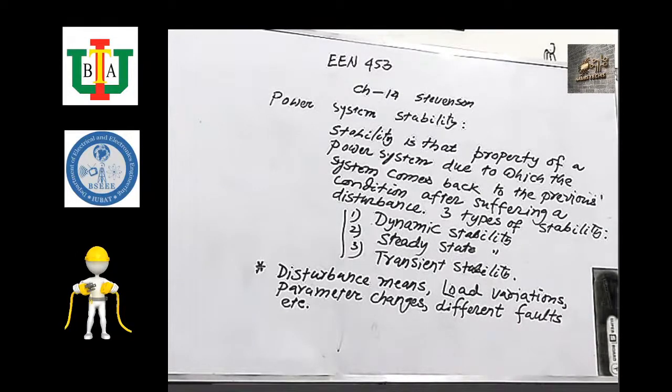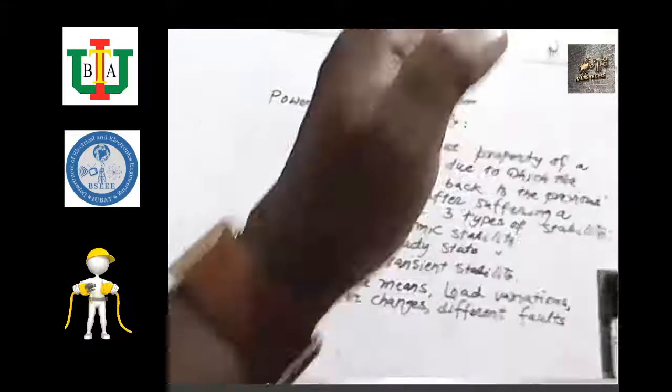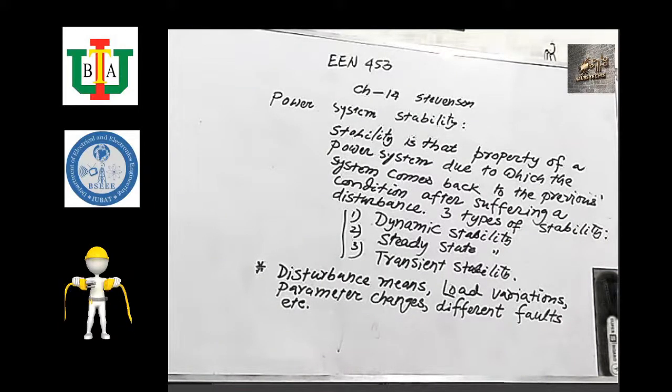Now you see that when there is a disturbance, at first the machine gives a very heavy swing, heavy oscillation. Understand? When the machine is in synchronous condition at constant speed, it is in a very, very healthy mood. But when there is a large disturbance, suppose a fault, due to that fault, the machine swings very much. In Bengali, I want to tell you, the machine starts swinging heavily then. Do you understand oscillation? When there is a fault or disturbance, the rotor gives heavy swing.